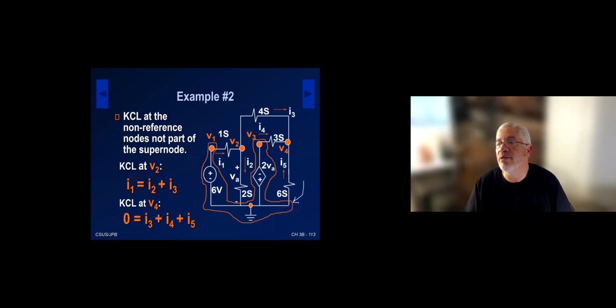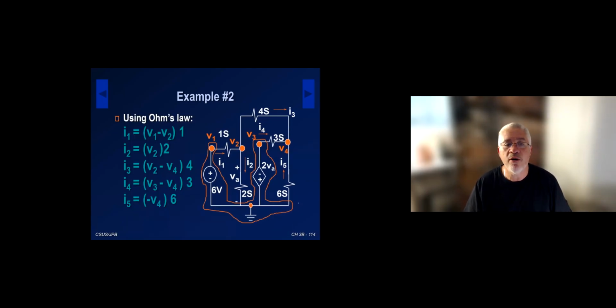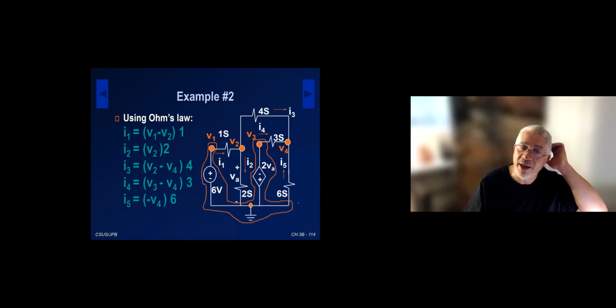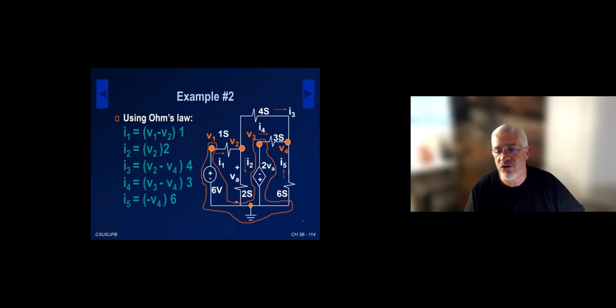The rest of the problem is pretty similar, with Ohm's law for the current on the resistors, paying attention to the passive sign convention and noting that I'm providing you admittances. So it's current equals voltage divided by resistance, or current equals voltage multiplied by admittance. That's why you see the multiplication by the admittance of each resistor.